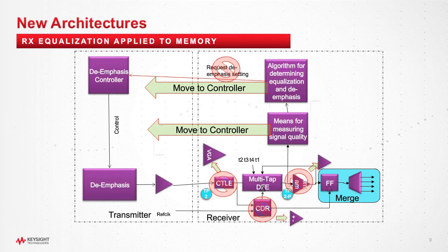There's also in PCI-Express a clock and data recovery unit, because while there is a separate reference clock that's supplied on the bus, it's not really the one that is used to time the actual data transfer. That clock is embedded in the data itself. The reference clock is used just as a general clock for the logic, and also to help deal with things like spread spectrum clocking.